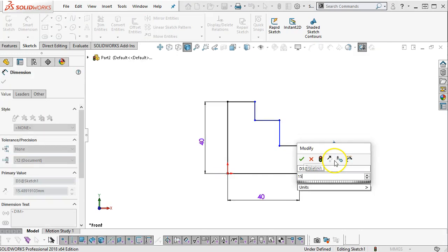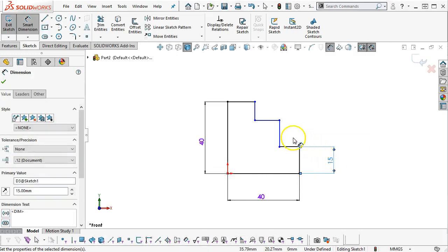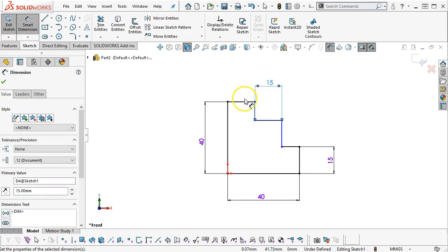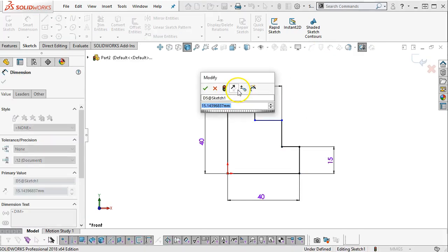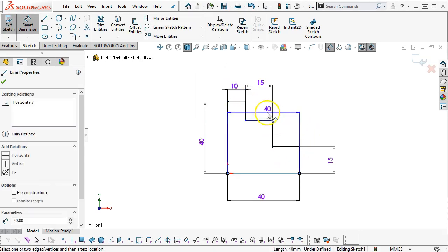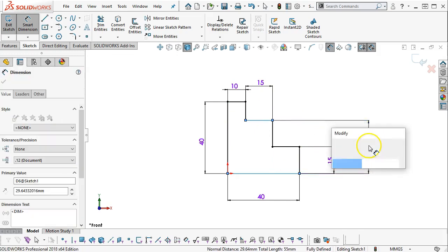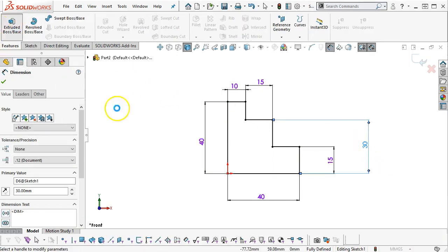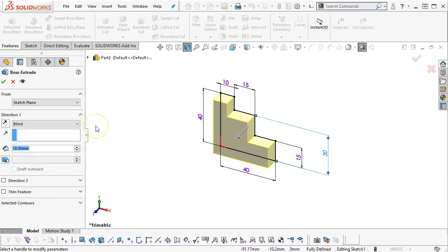All right, throw some dimensions on this. Still staying with the design intent that we're going to just build in basic geometry. There's nothing here that we are going to start in on the relations with just yet. All right, and then depth of 40. So our 2 blocks.